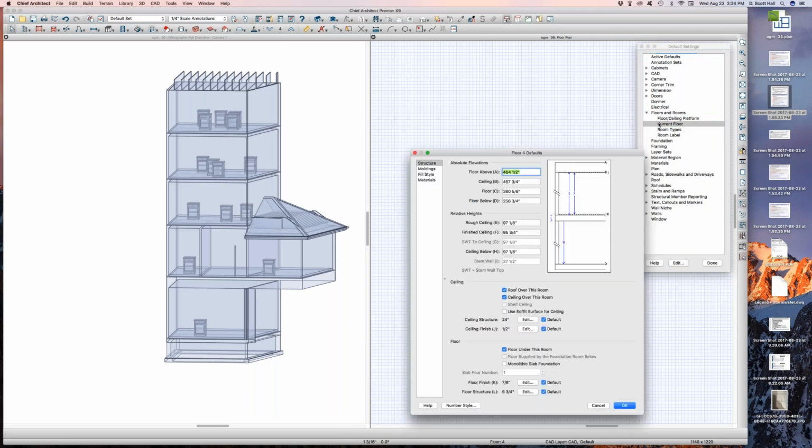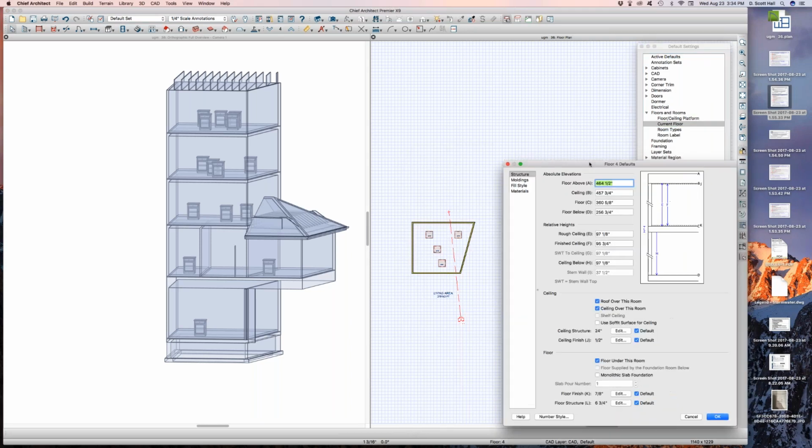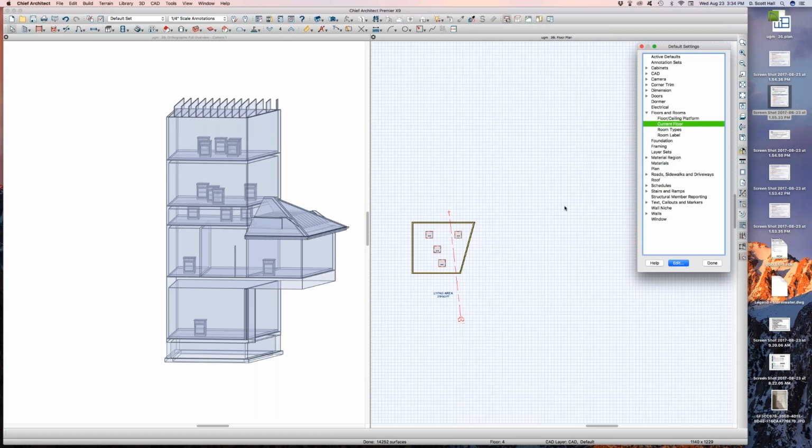Okay, here's the. I'm going to change a floor. I'm not changing it plan wide. It's only per floor. I'm on floor number 4, and I'm going to change floor number 4 to 300. 1, 2, 3, 4. Only one floor is going to move. Number 5. Hit your tab key. There it is. And that goes back to what Glenn said.